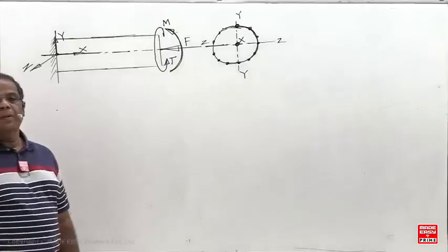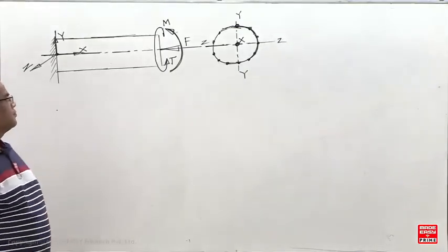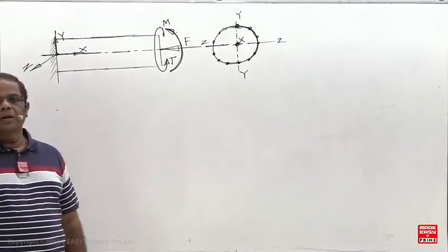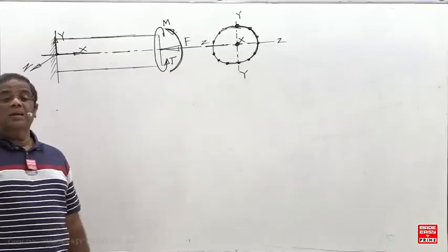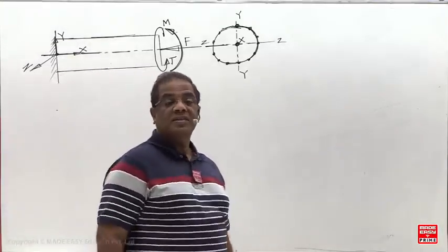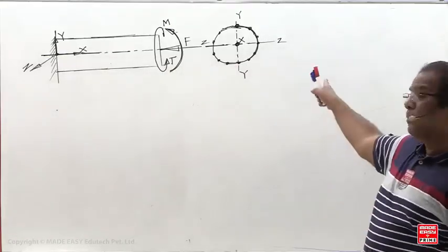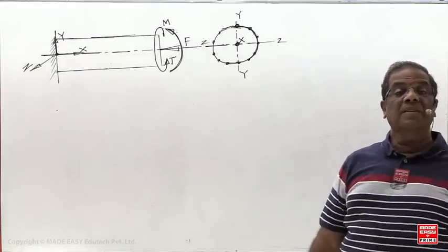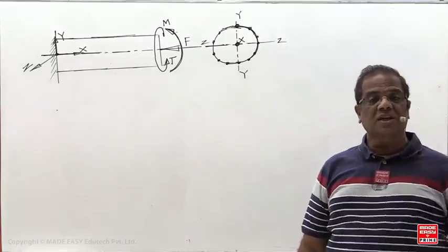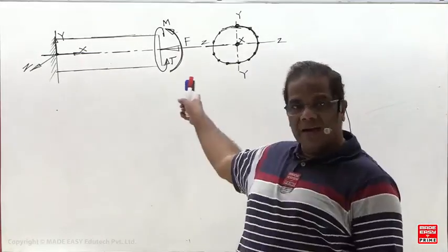So what should be the first step? First you have to identify the critical point, since principal stress should be calculated at the critical point. But the first step we have studied is the critical cross section. In a prismatic member, which is the critical cross section? At which cross section are axial load, shear force, bending and twisting maximum?